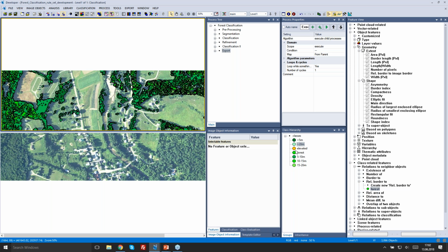So what we've seen in this webinar is an example of what we call knowledge-based classification. The developer, in this case Matthias, is defining the class definitions based on his expert knowledge of remote sensing of this particular image, of the classification results that are desired. It is also possible to do supervised classification within eCognition, which then would require such training data sets, and these training data sets can be created fully within eCognition. You can also import training data sets from a shapefile source to use in eCognition to train that classifier model on what to look for.